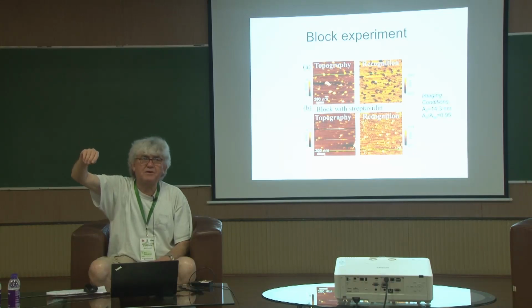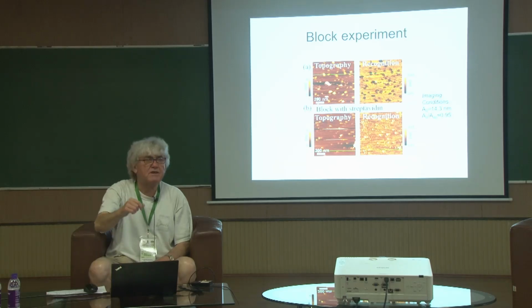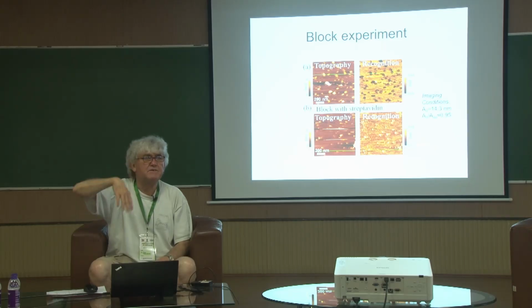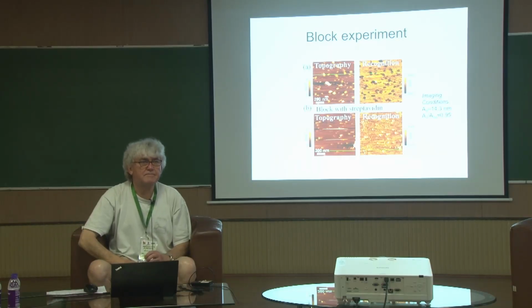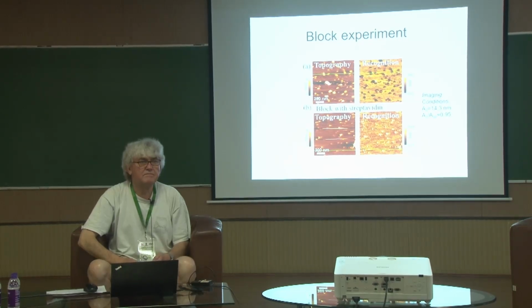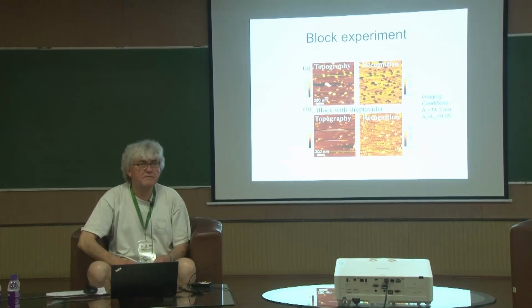And for spectroscopy, you need to do statistics anyway. TREC imaging is always faster than peak force, because it's a resonance technique, and peak force is a non-resonance technique. So with each cantilever, TREC imaging will be faster than peak force. I see. I was just wondering because the Q factor was very low, about 1, so I thought maybe doing it off resonance. But yes, your point I understood.